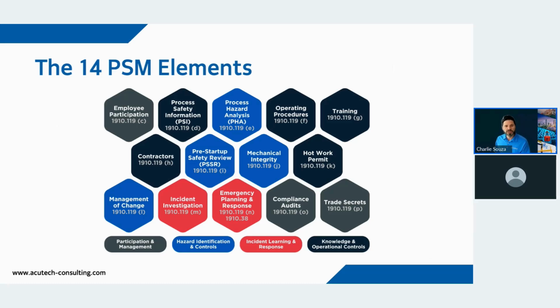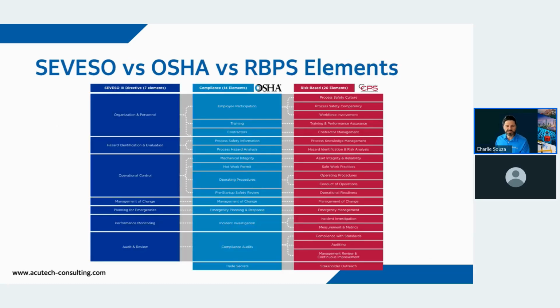In other words, you need to have not only a PHA or not only mechanical integrity of your basic instrumentation, but you need to keep 61511 in mind and keep documentation, keep records of everything that involves your safety instrumented systems, instead of leaving them split, right? Assuming that the other team, the functional safety team, is doing that audit, is doing that